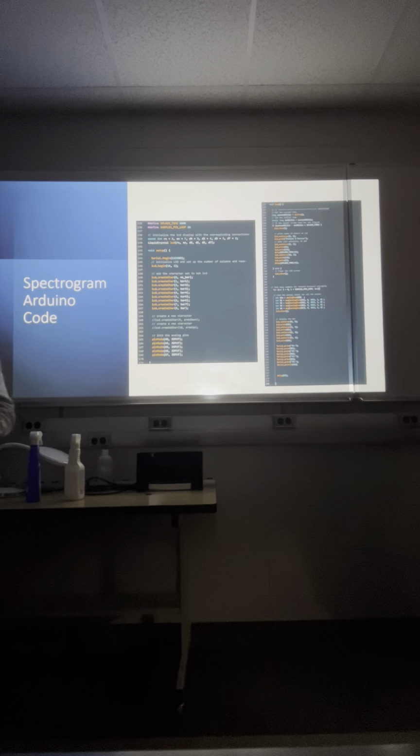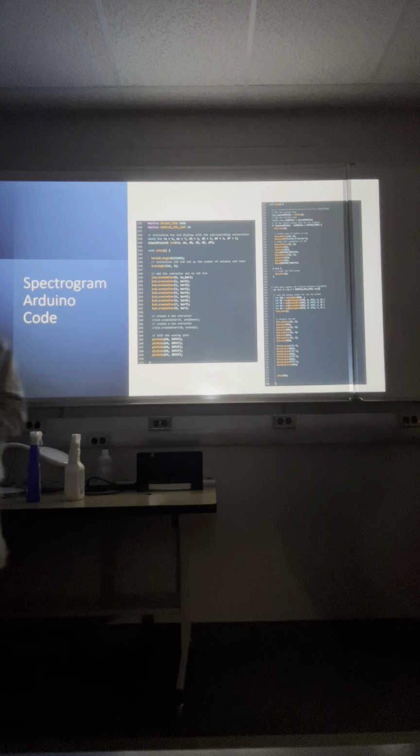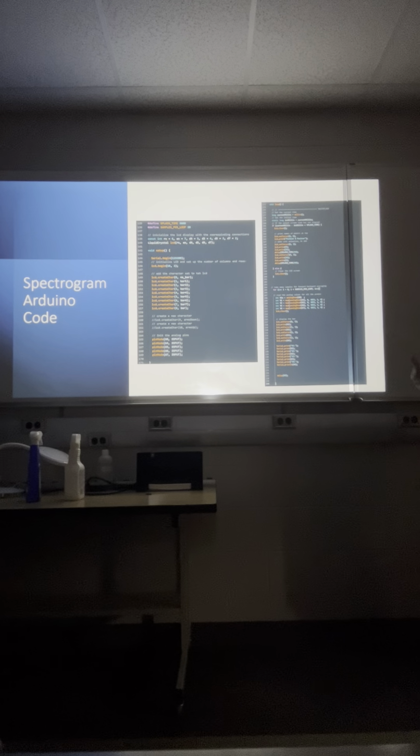But in theory, with an impedance matching transformer, you could have your circuit work with any speaker and still have maximum power transfer. The other thing that we were working on, which is what we originally presented as well, was the variable bandpass tuner. Sadly, we weren't able to get it working on breadboard, so we decided not to go through with it for the final implementation. But this is still something that's deep in my heart, so I still definitely will be working on this EVT later.